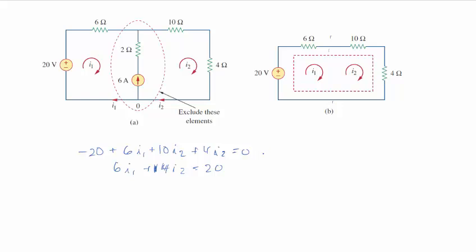But now, in order to solve it, I am going to apply Kirchhoff's current law to node 0 in the figure. This is where it's a little bit tricky. Here's node 0 in the figure, and when I do that, I have I2 equals I1 plus 6. So that's what's happening right here. This goes in, this is out and out, and so I get a second equation here, like a constraint equation. Now I have my two equations and my two unknowns, and I can choose my method to solve this equation.